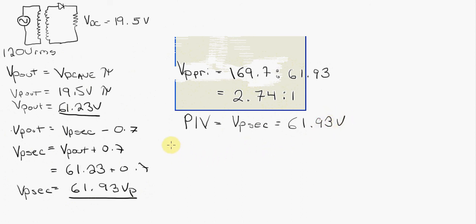And as I said, if I knew what the connected load was, so in this case, if I knew the laptop with a dead battery drew so many watts or so many amps, I could then do the math and figure out how much current is going to be flowing through here, peak, and pick a diode that can handle this much forward current, this much voltage, and this much reverse bias current. And again, you could now just make this power supply if you needed a particular voltage.